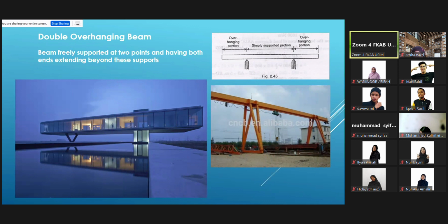Some examples. On the right here is a crane gantry. They use the crane to move around a casting yard, for example in IBS, the industrialised building system, especially when they use a lot of big wall panels, and then they need the gantry to move sideways to handle the casting of such big walls. Casting is where you pour concrete and let it dry and cure from wet to something solid.